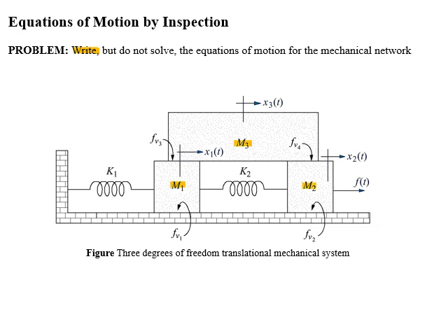Likewise, m2 can move freely if m1 and m3 are held stationary. Similarly, m3 can also move if m1 and m2 are held stationary. So this system has a degree of freedom 3, and we'll find three simultaneous equations of motion with the help of the inspection method as required in the problem.